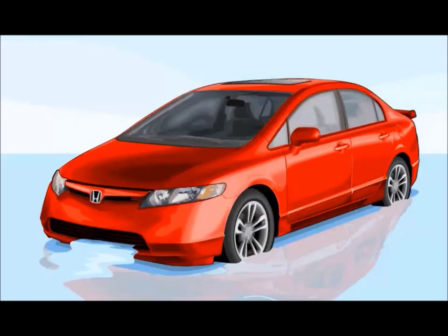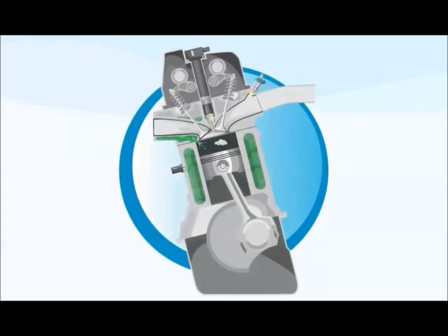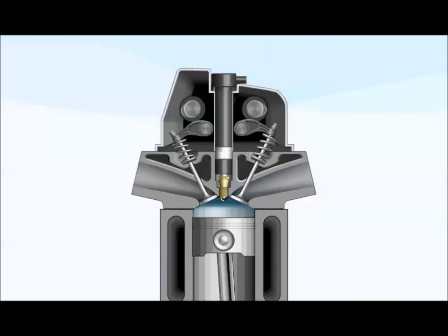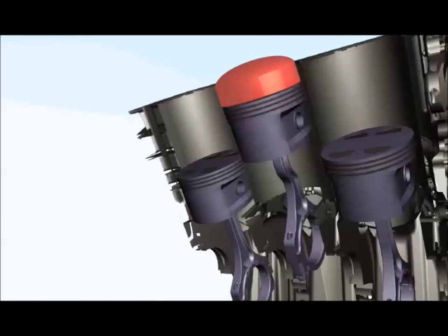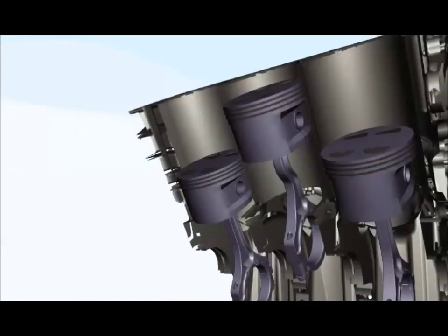Liquids such as rainwater, fuel from leaking injectors, or coolant from leaking gaskets can also damage the engine. When the liquid volume exceeds the combustion chamber volume, the piston stops prior to top dead center, creating a hydrolock. Because liquid presses evenly on all parts of the cylinder, the piston top and combustion chamber does not show any marks or nicks. Instead, the connecting rod bends to make room for the liquid.